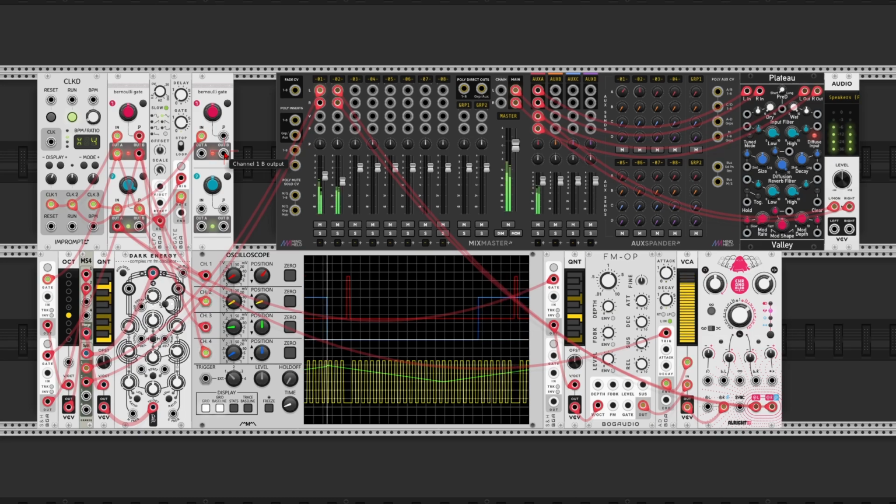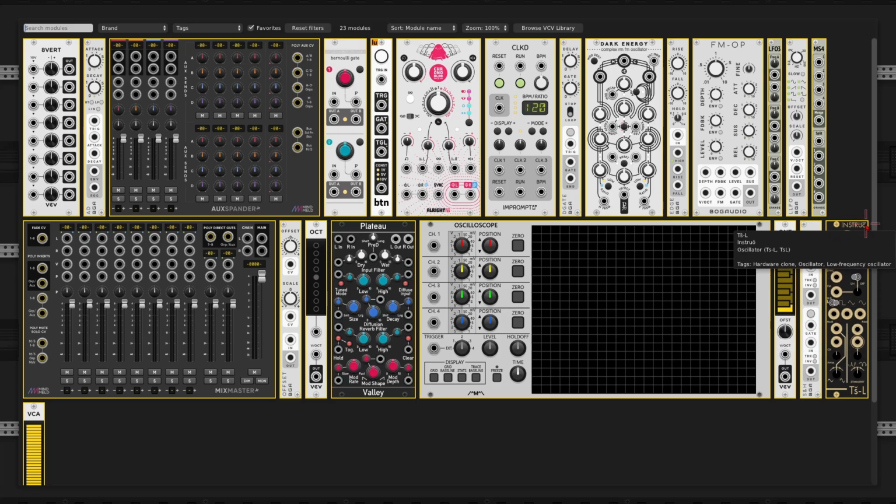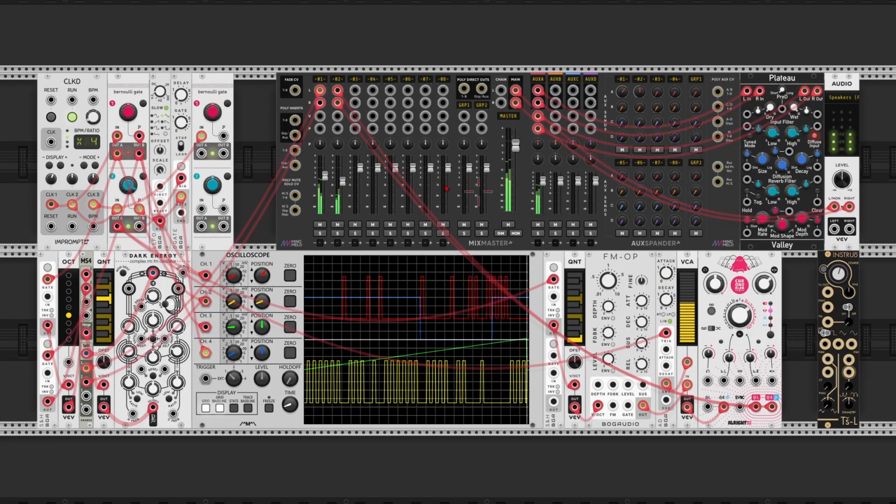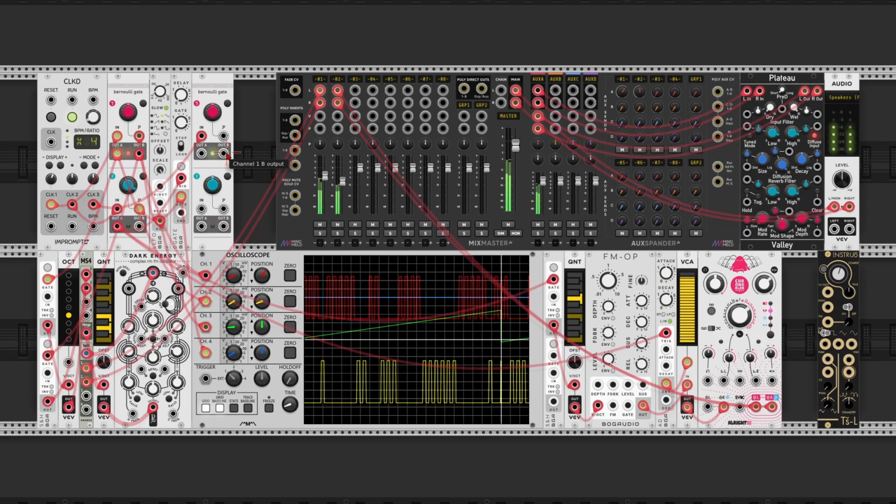I'm going to use this to make a bass voice switch between a C and a G note. Playback will be done by the Instruo Ts-L module, which will have to provide a volt per octave input. When the B output is not active, it will be 0 volts, so that already matches the C that I wanted to play, but when the output is active, it will be 10 volts, which is a C 10 octaves higher, while I want a G, so we'll have to modify that.